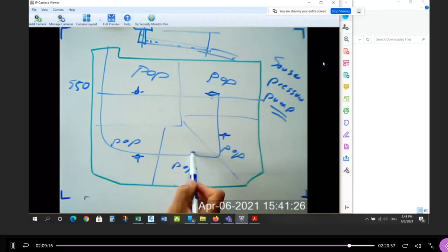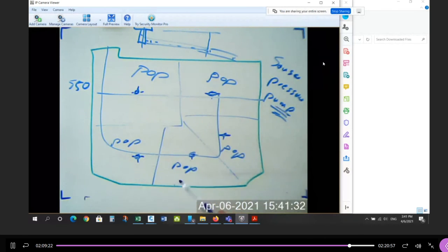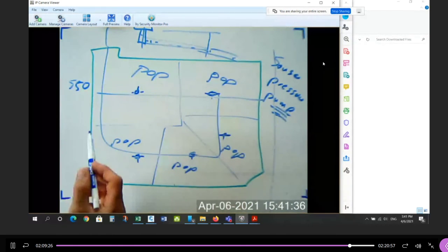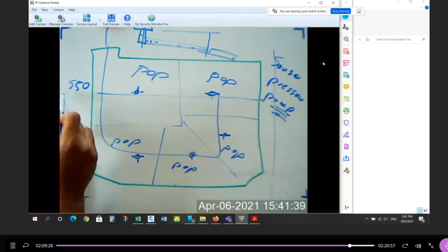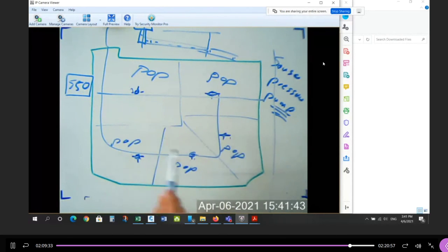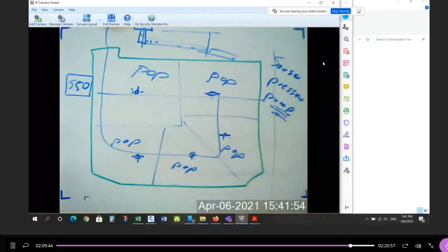So you have to know the elevation at all the hydrants, and then you charge the system with a pump curve based on the system you're a part of, connecting to this existing one and this existing one. Then during normal operation, you cannot exceed 550 kilopascals of pressure at each node. So with no fire, make sure that none of the nodes, none of the hydrants, have a pressure higher than 550. If it's higher than 550, you might want to consider changing some of the pipe sizes. Typically, you have to make the pipes bigger.